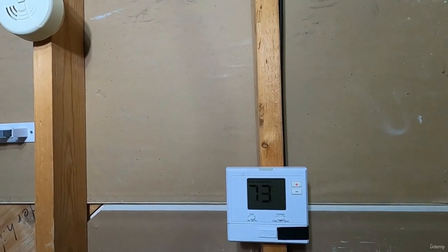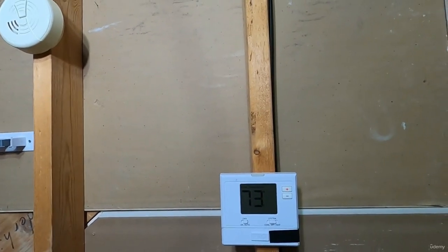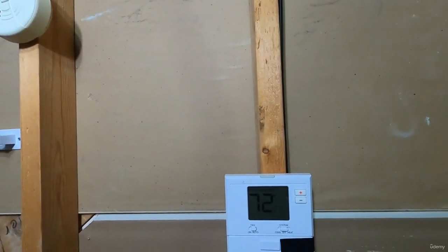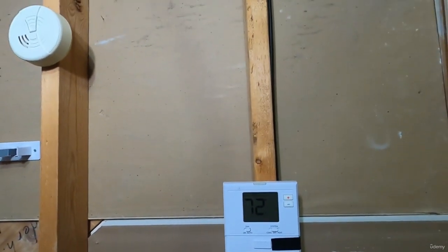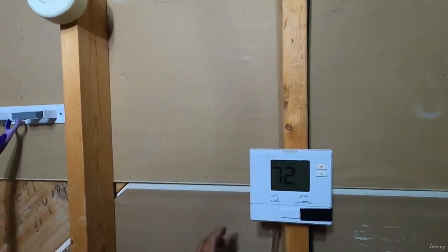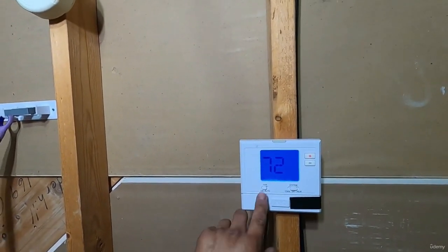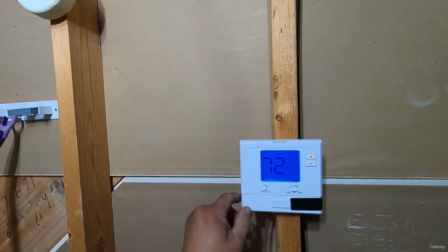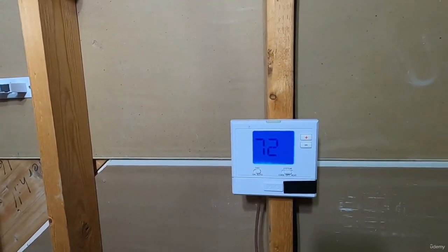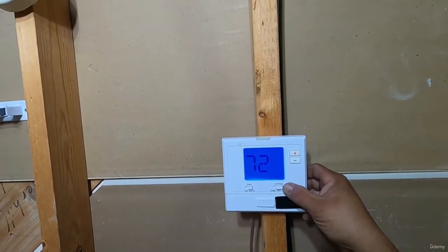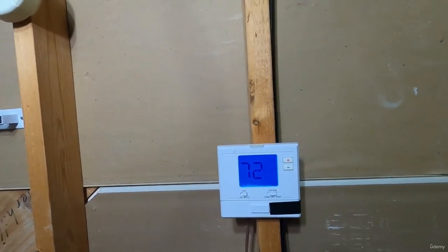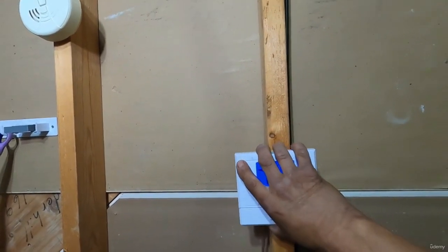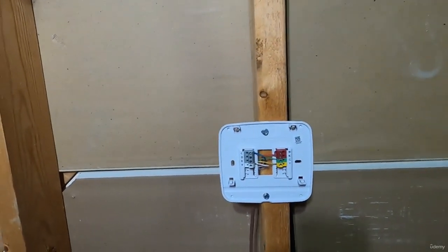All right, guys. Hey, we're going to cover the thermostat, and this is basically where it all begins. This is going to tell your system when to turn on, when to turn off. And you're all probably familiar with the thermostat. You got your fan setting. You got an on or auto. On will be, it just runs 24 hours a day. So most of the time you have that on auto. And then you got your cool, off, and heat. So we're going to show you how to test this, see if it's working properly. But we're going to go ahead and take this off and show you the wiring here.